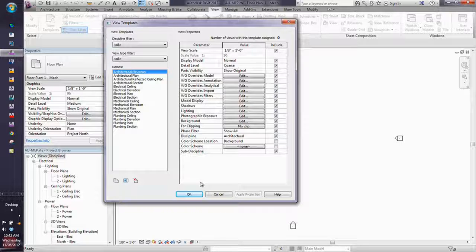Different level heights. If you ever do a project where you have multiple buildings in one file, like we do in our water treatment plants, I could have a building over here that's at building elevation 300 and another one over here at 301. And if you set your view range up in your templates to start at the current template and then go to the next level, what winds up happening? There's a really short view template in there. So we started turning view range off. And that's one of the things that you can set up in the default. So when you get the default set up like this, you want to make sure that you have those settings already in here.